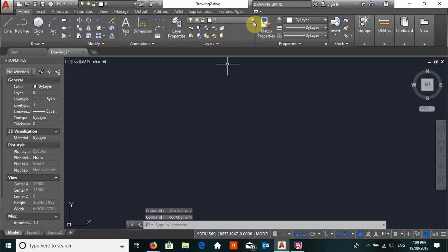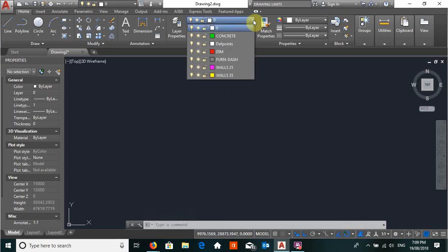Now we are going to make our start with our exterior walls. It says here, drawing the walls: use the polyline or PL tool to complete the outline shown in the example above. You may start at absolute coordinates 6,900 as an X coordinate and 6,000 as a Y coordinate, and draw in an anti-clockwise direction. Use external brick measurements. Refer to drawings for major project for dimensions.